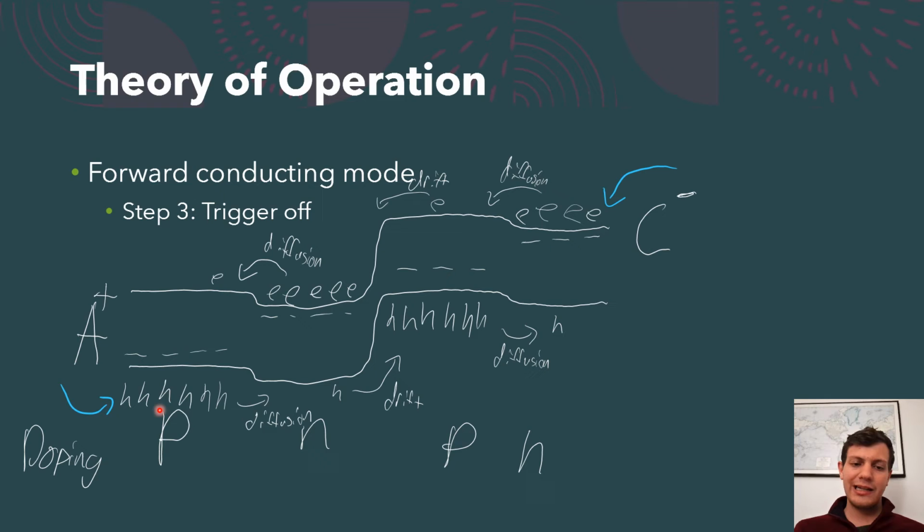where they're going to get annihilated with some holes in this p-doped region, which more holes are going to be replenished by this arrow over here. So it's this whole cycle of moving down the device and recombining that really provides the current that goes through this device.